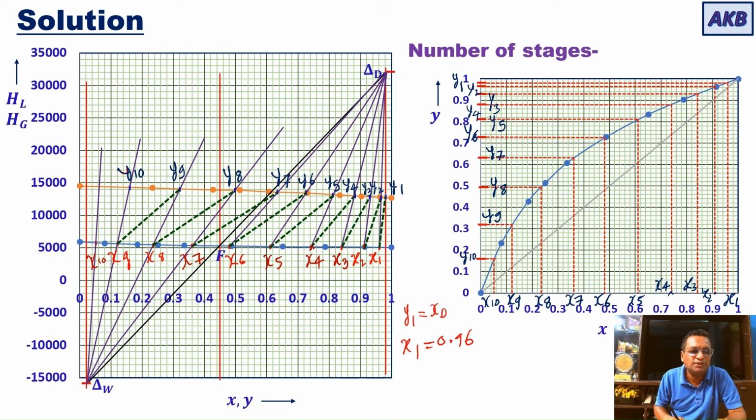And then I'll draw a construction line through x10, and x10 and y10 will be connected by a tie line. In that process, we get this point. We are going to read it as y11, sorry. So just a minute. Let me change the color. So this is y11. And what is that value? You can check. It is 0.02, 0.04, 0.06. So I'll come back with this value to the distribution diagram.